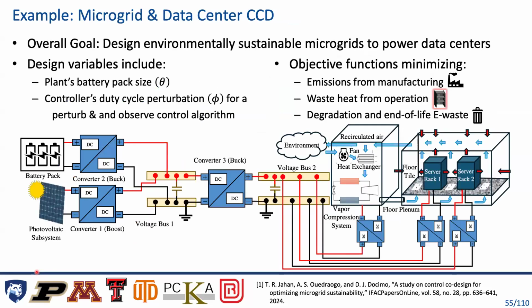For our second example here, again, I like to keep my feet on the ground, and let's go with the hot topic of microgrid and data center control co-design. What if you want to design your data centers to be a little bit more environmentally friendly, right? So let's say you're just trying to size your battery pack on the microgrid side for now. You have a model-free perturb and observe based controller where you're trying to choose the duty cycle step.